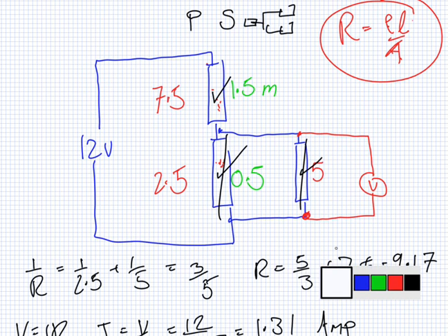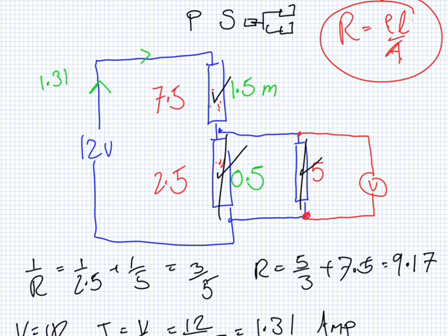So that's good. We know that it's 1.31 amps. So, let me see, we would like the voltage here. So the voltage V equals IR. We know the R, so we're finished if we know the I. Is the I 1.31 here? It's not, because look what happens. It's 1.3, 1.3, 1.3, but then what happens here? It splits, doesn't it? So it's not 1.3.